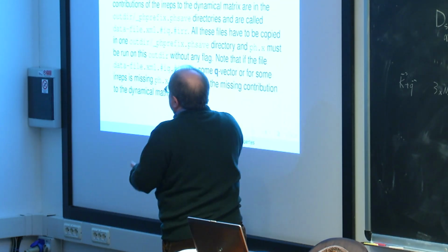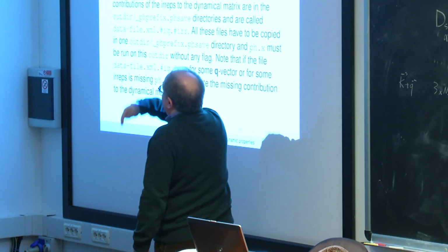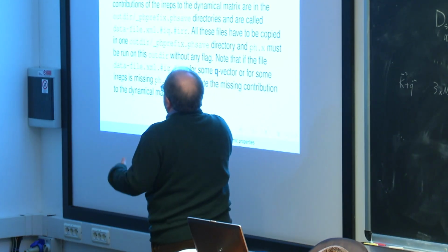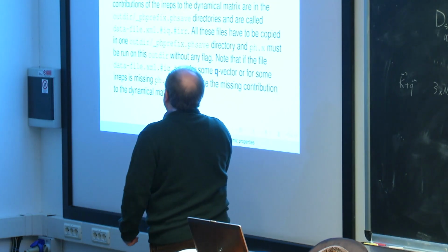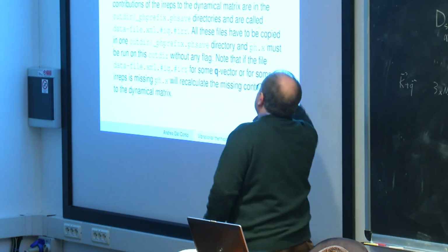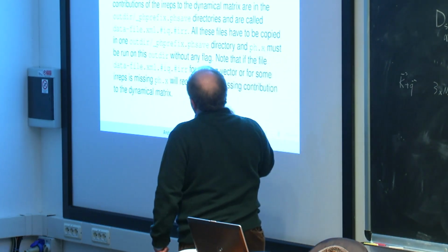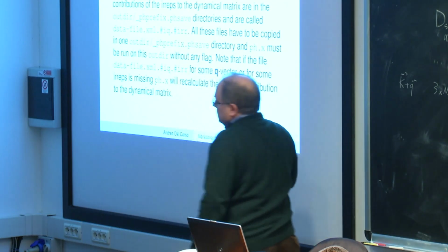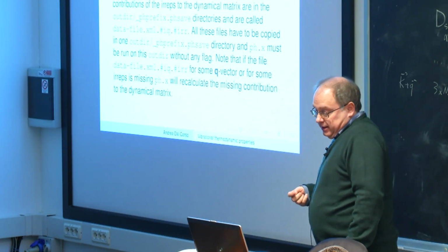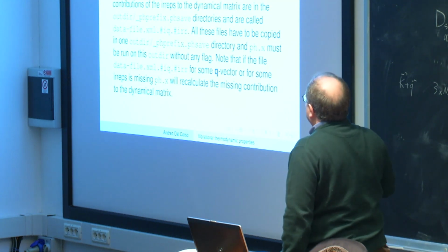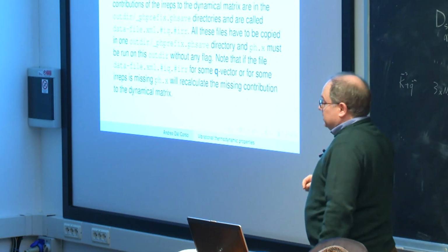And you have to copy these files by hand into the outdir where you will then run a ph.x run that collects all the results. There is a grid example that does this, but the machinery is slightly complicated and relies a lot on the fact that the user must know what he is doing.